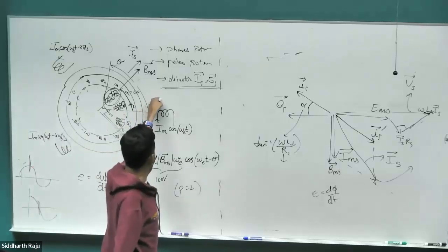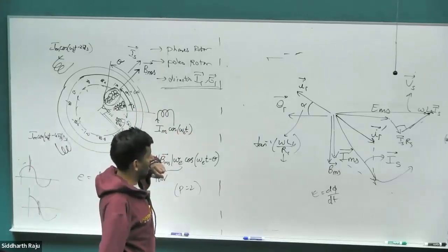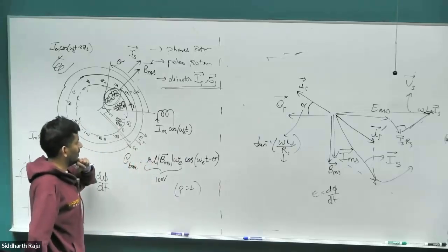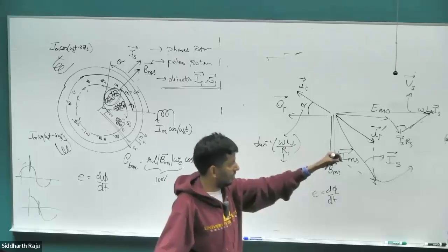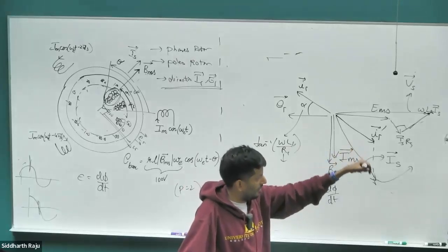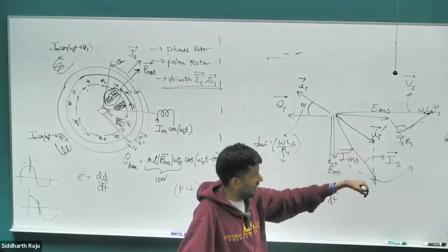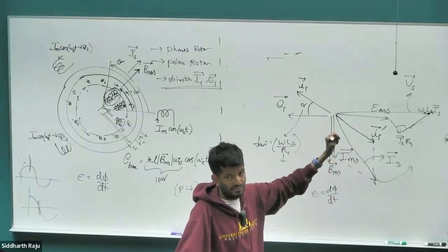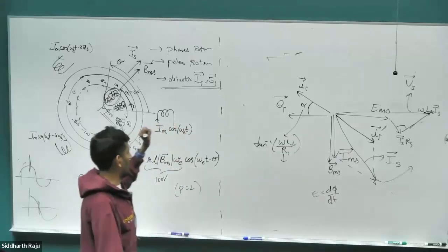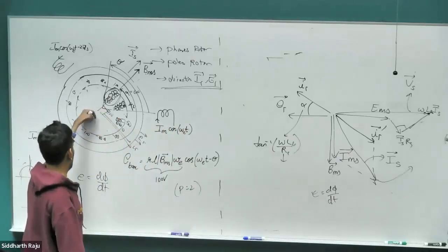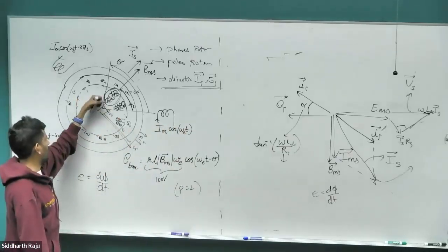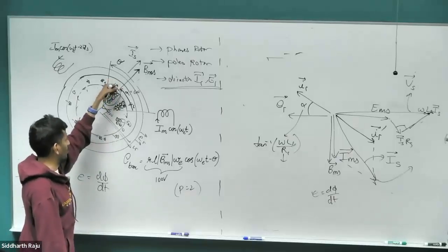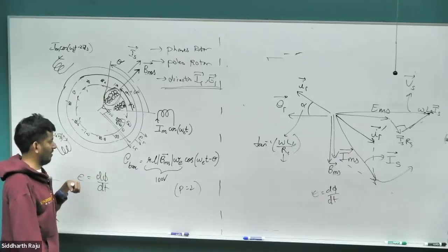So here again, when we address this, I said when we look at the phasor diagram, we'll again make the case that it has to be behind by 90 degrees. I think that is clear because if you look at the phasor diagram there, when you have your current going in the perpendicular direction, IM, the EMF induced on the secondary side was 90 degrees behind it. Right? Nothing to do with space vector notation. When we come back to a space vector notation, we said that we'll assume the rotor coils to have this kind of profile, even though they are individual bars, so that they reflect what's happening on the stator, and we'll draw a space vector along this direction.